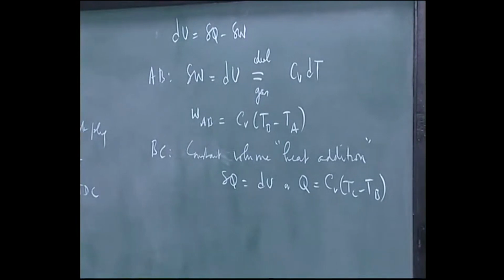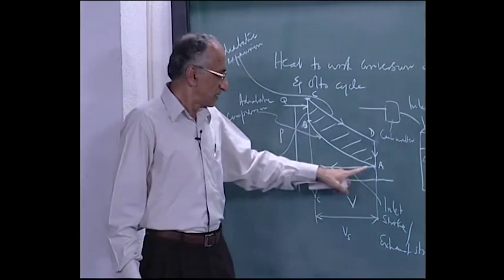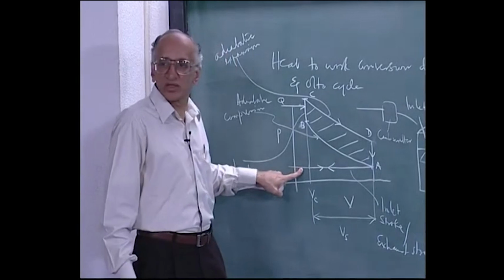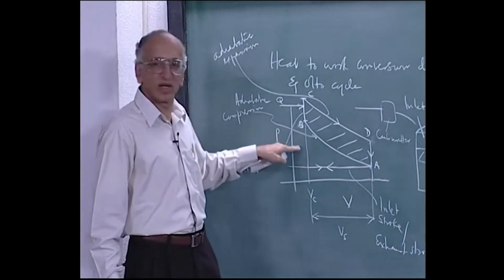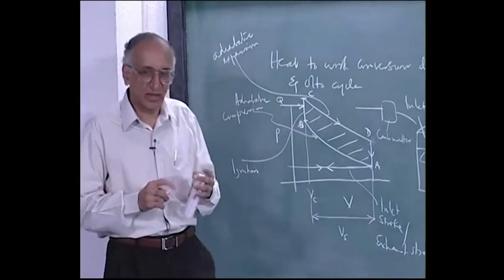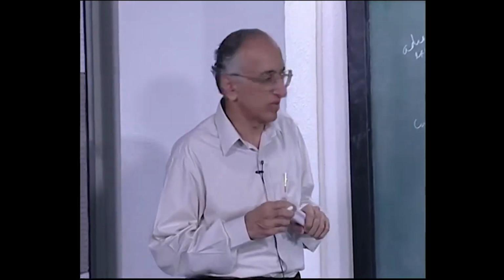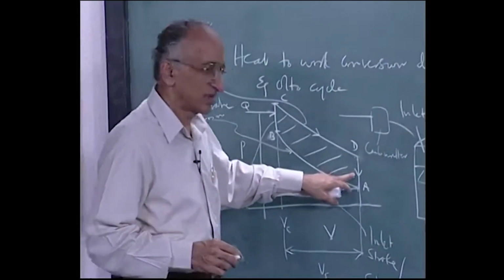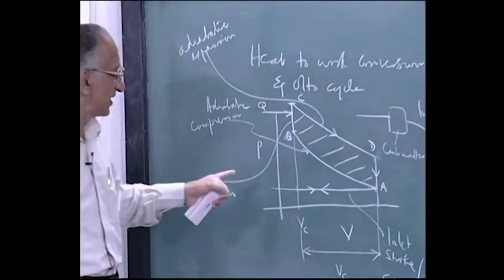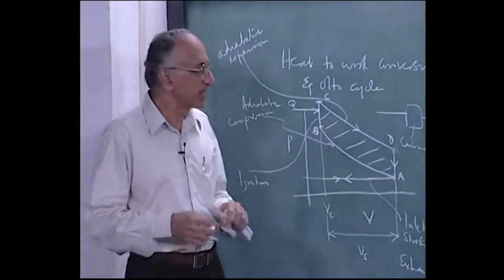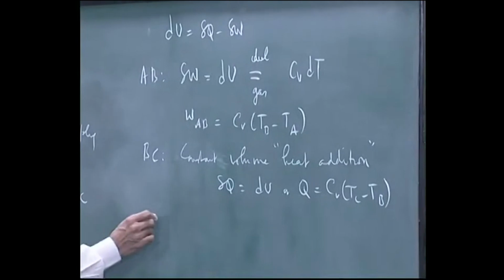The conditions at A are known, the pressure at the intake is usually atmospheric. And when you have a supercharged engine, all you do is have a compressor and raise this level, and I can show you that gives you more power per cycle, but at the cost of more fuel. It does not make it more efficient, but you get that initial kick by supercharging your engine, putting a compressor in the inlet, compressing the inlet air and sending it in. Then CD